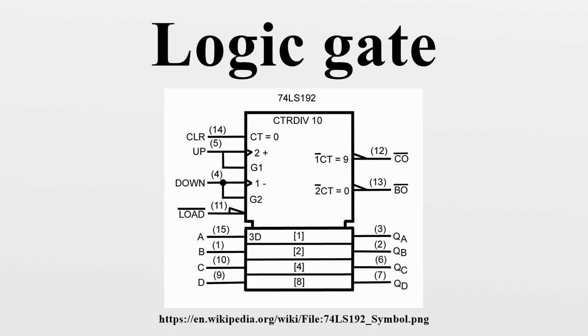The output of one gate can only drive a finite number of inputs to other gates, a number called the fan-out limit. Also, there is always a delay, called the propagation delay, from a change in input of a gate to the corresponding change in its output. When gates are cascaded, the total propagation delay is approximately the sum of the individual delays, an effect which can become a problem in high-speed circuits. Additional delay can be caused when a large number of inputs are connected to an output, due to the distributed capacitance of all the inputs and wiring and the finite amount of current that each output can provide.